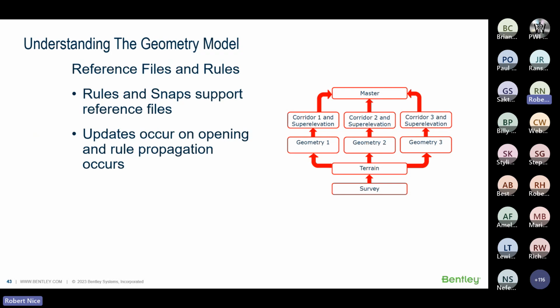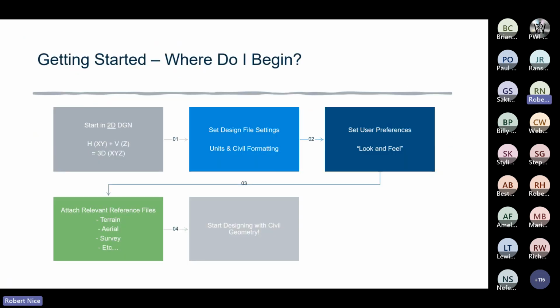And then that all goes into the master. There's a deliverable file which has 3 different geometries, zones 1, 2, 3, and I see everything. Of course, if geometry 1 changes, it all flows through and the master will get the update. Basically, it's the coordination DGN at the very end, which has nothing live. It's all just referenced, and all of that can be sent out using iTwins and iModels.